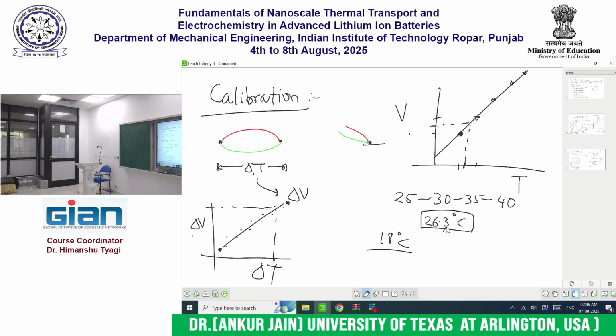I would say that if you are going down to the first decimal point, then your calibration should also have been done with plus or minus 0.1 degrees C. So I'm asking too much here, but you should be doing your calibration at 25.0, 25.1, 25.2, and so on degrees Celsius. Most people don't do that much. I think that if you're going down to 0.1 degrees C, it is perhaps okay to measure at 25, 26, 27, 28, 29 and so on.